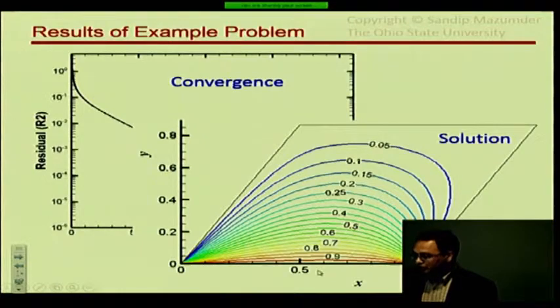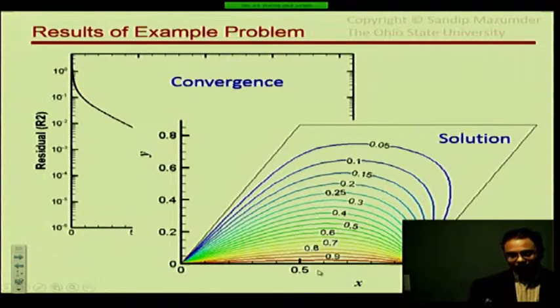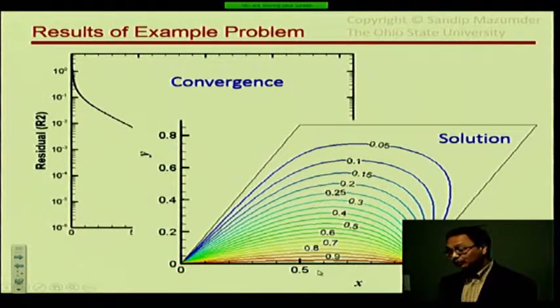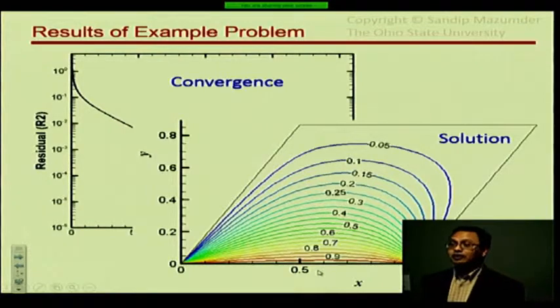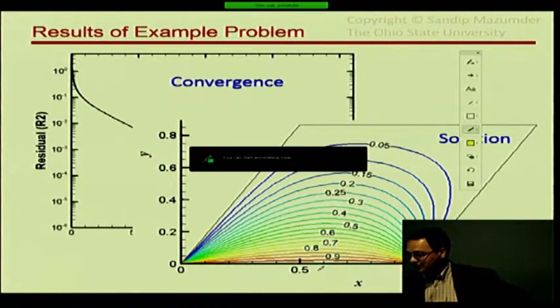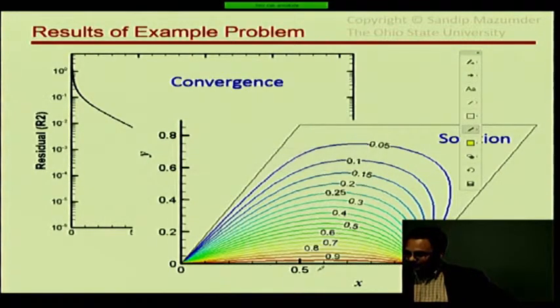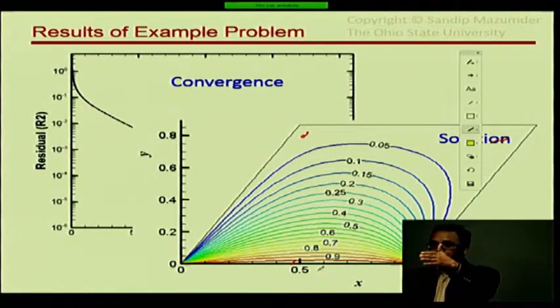So as I was saying, one of the things is making sure that all the directions of your surface normals, tangents, and so forth are consistent and done the right way. If they're not done the right way, here is, for example, what you might get. This contour that you see, okay, this is actually the right solution, because what happens here is, because this is a far corner, the information of this boundary doesn't go to that corner as much as it goes to this corner, which is closer to that boundary. Okay, so the contours are kind of skewed to the left.